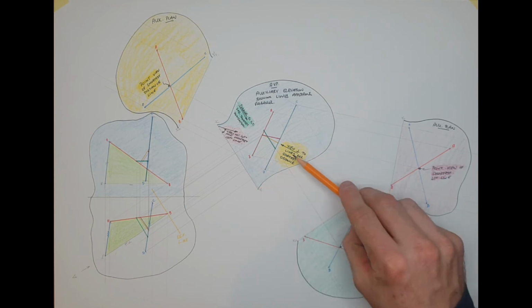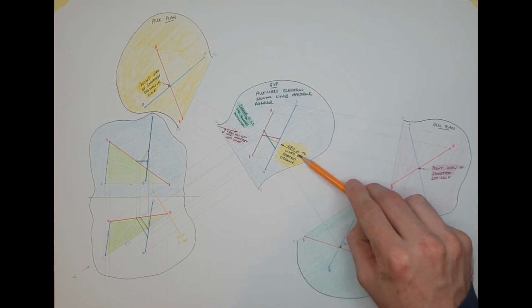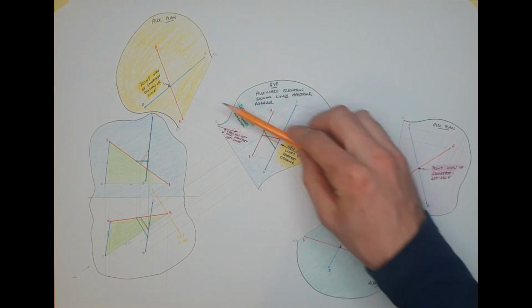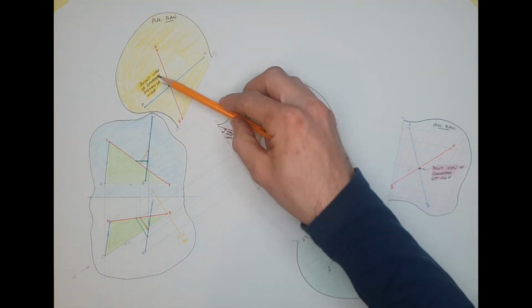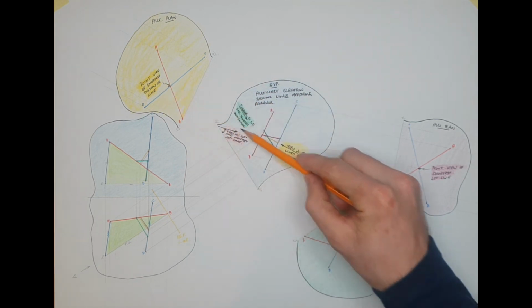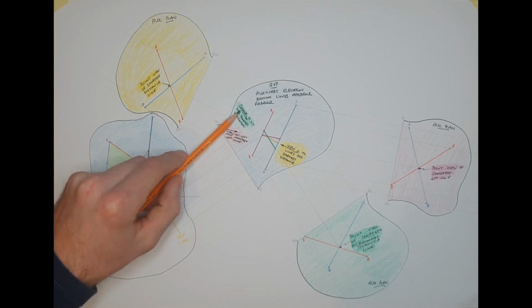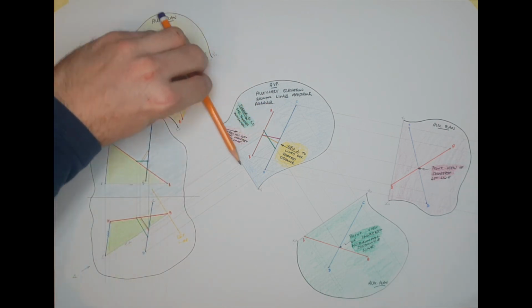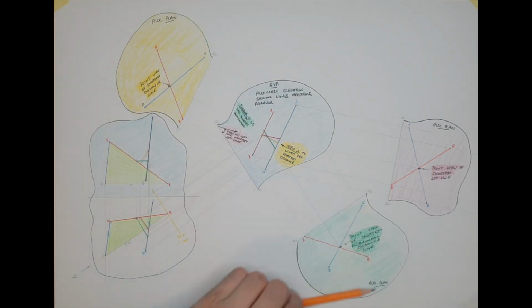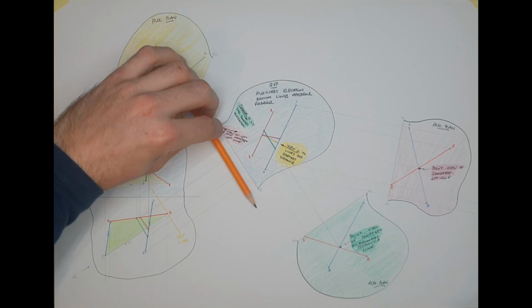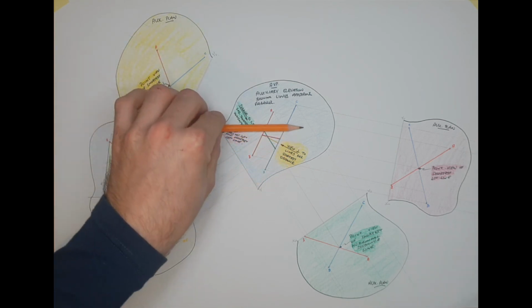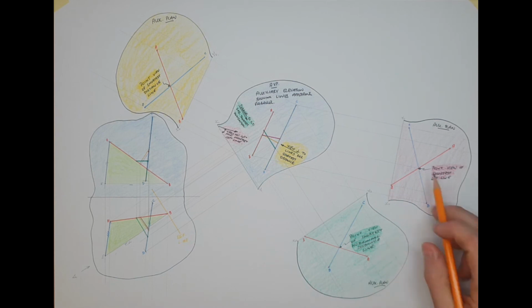If you're looking for the view perpendicular to lines for the shortest distance, that's what I have here, and my arrow, and that's the yellow point with the yellow plane, which shows the point view of the shortest distance line brought back through. Parallel view, parallel to x and y1 for the shortest horizontal, so parallel to the x and y1 viewed down here for the shortest horizontal distance. And then finally, view at 45 degrees up for the shortest 45 degree line, shown as a point view and projected back through. So 3 different solutions there to 3 skew lines questions, all on the one page.